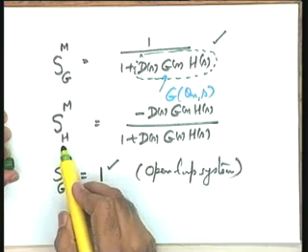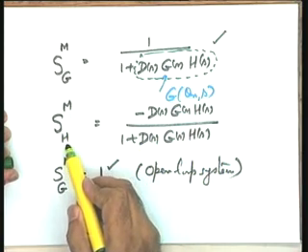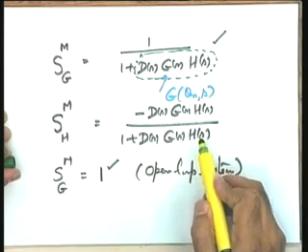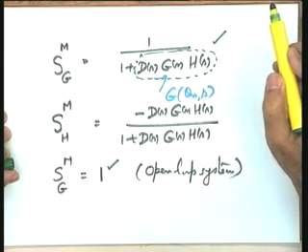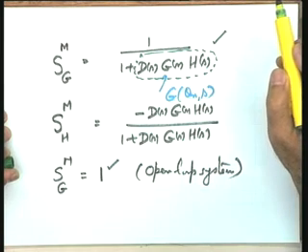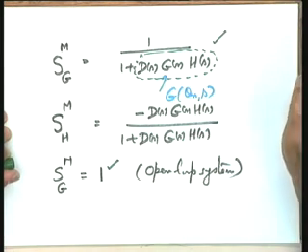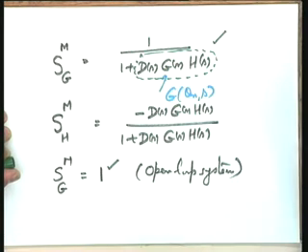Okay? Look at the sensor. Please see, if I increase the loop gain, the sensitivity of M with respect to H tends to 1, which indicates that the closed loop system is highly sensitive to parameter changes of the sensor. Therefore, at the design stage as a control engineer, we have to be extra careful in selecting the sensors. The sensor should really be a robust and stable sensor, that is, the components or the parameters of the sensor should not change with environmental and other conditions. This should be our selection as far as sensor choice is concerned.